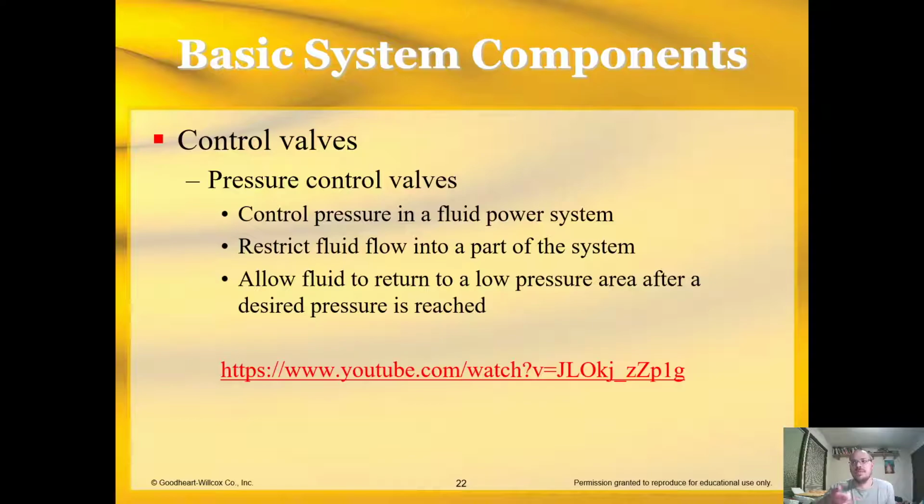When we control the pressure on those pressure control valves, we actually set, I like to say, limit the system pressure, because the pump's trying to push out as much pressure as possible, really. I don't have a good image right now, but basically you're allowing some of that fluid to divert back to your reservoir to lower the pressure, and whatever is left goes into the system, right?